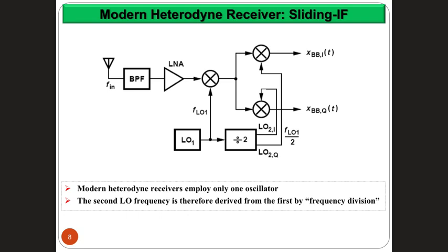If you decided, for example, that the ratio between your first local oscillator and second local oscillator is going to be divided by 2, and you are sure that the second one has to bring you to 0, and you know your input signal frequency, immediately it becomes mandatory that LO1 will have a certain fixed value. There's only one possible value to bring you down to 0 in 2 stages, given that LO1 and LO2 are related to each other by one being half the other.